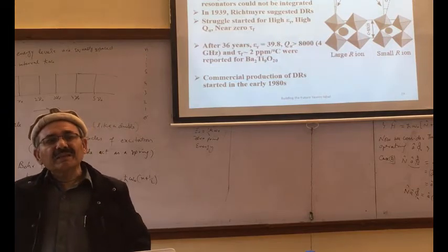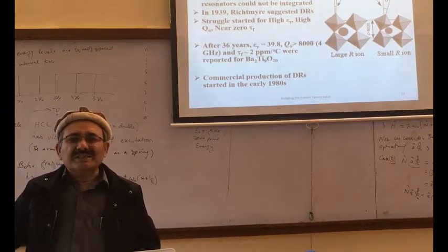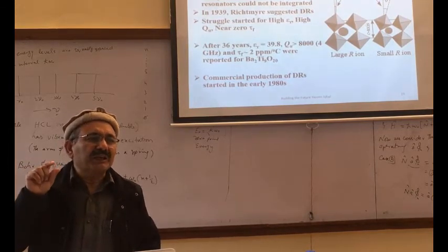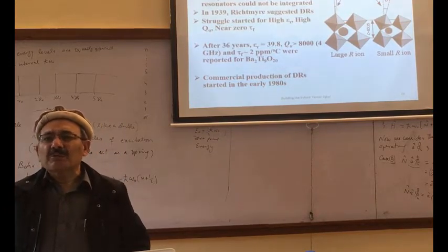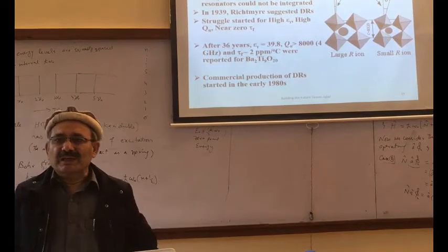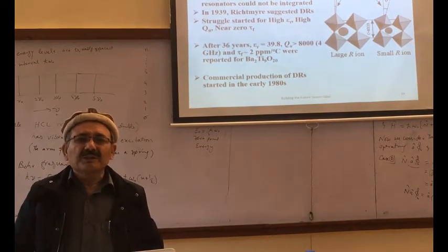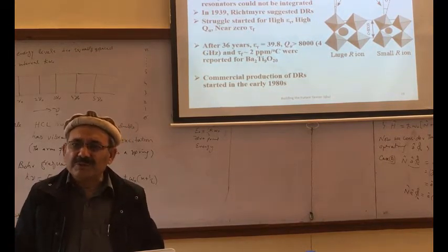Sometimes the signal travels a lot in free space and its propagation inside the component is very small. For that case, you don't need a very high dielectric constant. For example, for radar and antennae used for telecommunication, you can have a dielectric constant as low as 10 or 5.